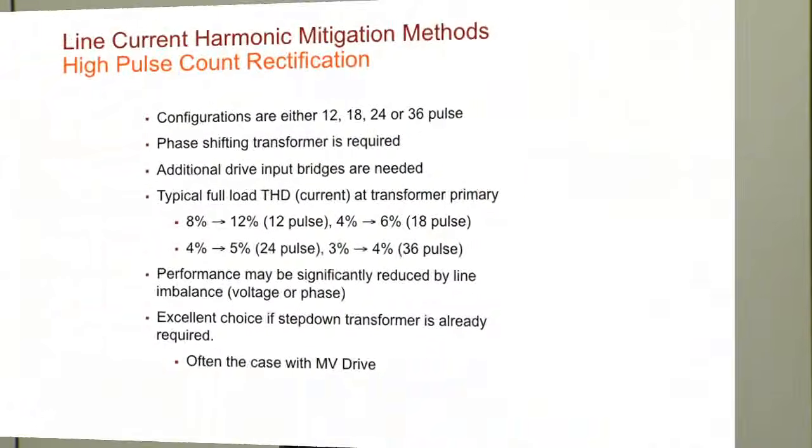The benefits from going to this guy, you're getting more hardware. That cabinet's getting larger. Now I've got a transformer I've got to worry about. I've got to size the enclosure big enough for that transformer. Also have more diodes in there. It's more complex. For a guy coming in to troubleshoot that, there's more components there, more things to go wrong. If I look at this guy, bigger transformer, more hardware. The benefit to going to the ultra-low harmonic drive is I don't need a transformer. I don't need those extra bridges there. The drive does that. Basically, it's all built into one package.